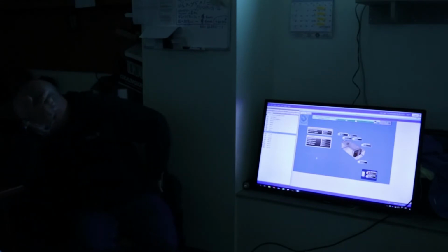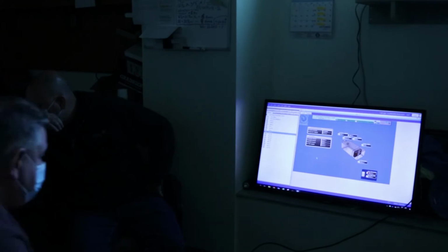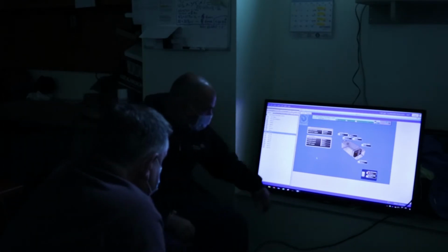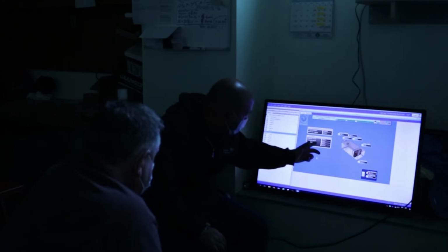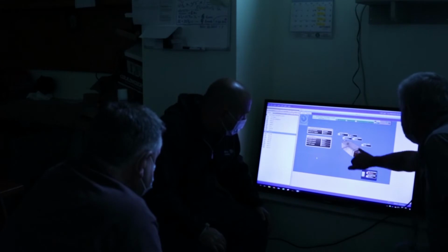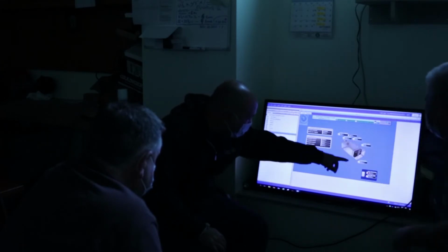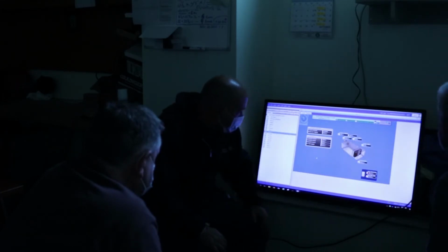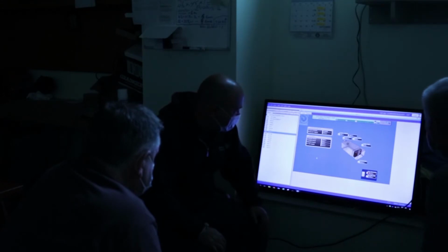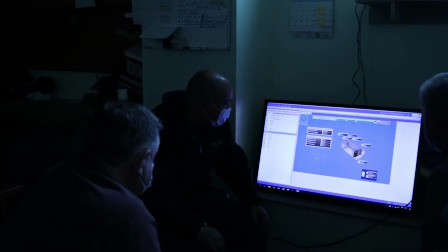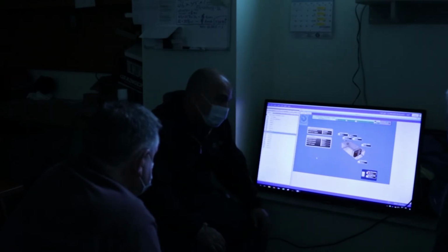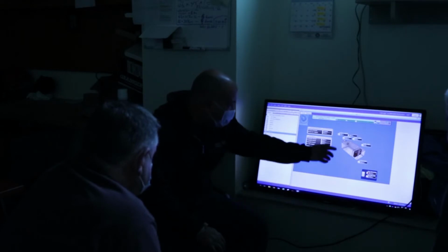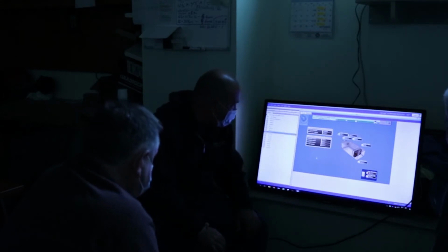Well, let's see what we got here. So what is this? We look at it, it's 81 degrees in the space. Everything seems to be below 54. Well, this is at 54, this is at 54.4. So there's no heat, we're not passing by any heat. Then there should be open more. Well, no, we're looking for 200 CFM, and we're doing 207. So, based on the size of the box, this is what these CFM set points are at.